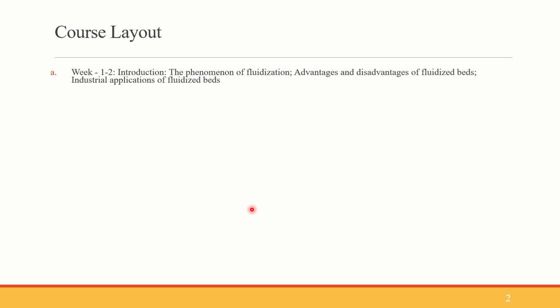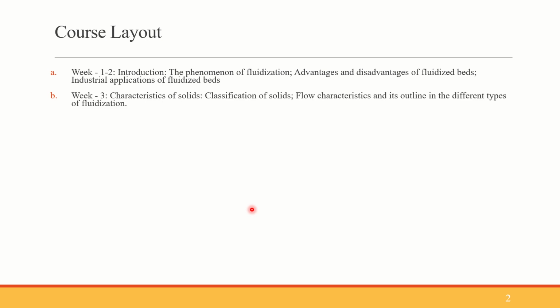So what are the disadvantages? We have certain disadvantages like the erosion of the particles, as the particles might escape, so that we cannot use higher costly materials in these applications. Later on, we have also seen how fluidized bed solids are classified into four classes by Geldart, depending on their size and the relative density between the fluid and the particles. And based on the class under which those particles fall, the particle behavior would be different.